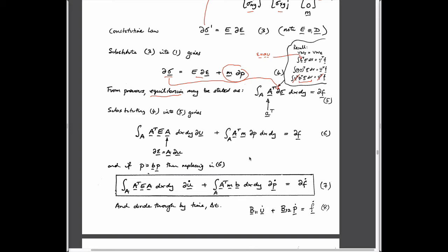Except what we could also end up doing is we know that we map nodal variables in terms of pressures as equal to shape functions and nodal magnitudes of pressures. And we already have these in terms of nodal values. And so if we make this substitution, then these are nodal values of pressures, and we have a new matrix, a matrix we actually haven't seen before.